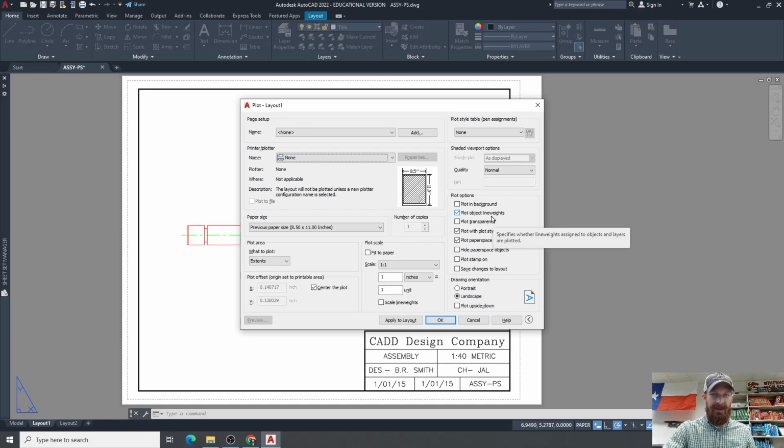So if I model a bracket or an axle and it's 4 feet long in real life, when I model it on AutoCAD, it's going to be 4 feet long on the computer, right? Not until the CAD drawing is plotted on a fixed size sheet of paper is it scaled to fit. So nothing is scaled until we plot it or print it. I hope we've driven that point home.